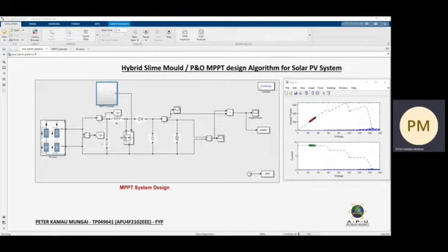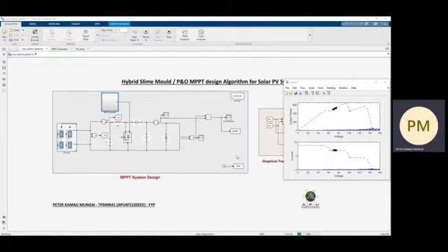And as mentioned before, this system consists of a PV array, which is connected in series to a boost converter circuit, and the boost converter circuit has an output voltage that is regulated by a duty cycle of the MOSFET. The maximum power point controller is used to extract the maximum power from the PV array and measures the current and voltage of the PV panel, thereby generating a duty cycle. This generated duty cycle is given to the driver circuit, which generates a pulse wave modulation for controlling the switching of the MOSFET.